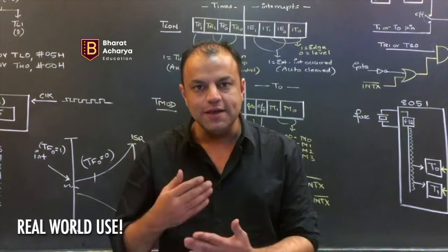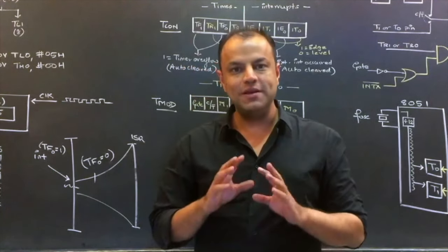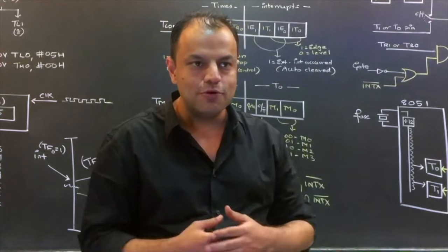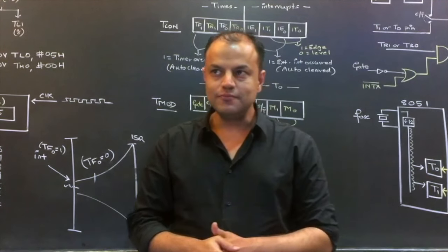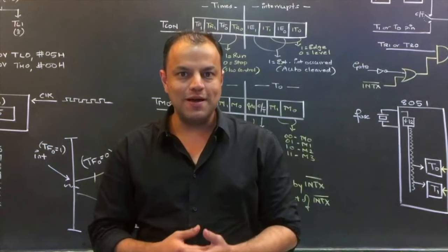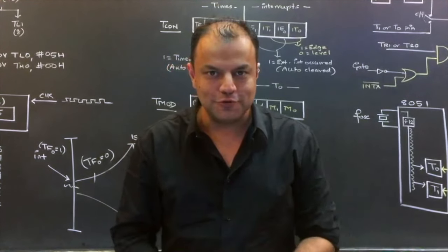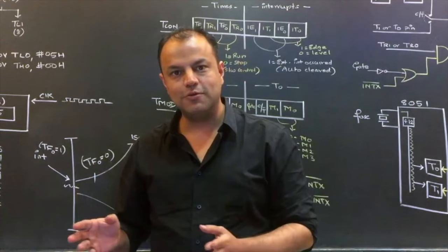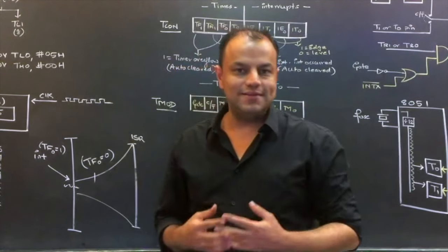So here you need a separate component to produce the delay. That's where timers come into the picture. Please tell me, did you understand why you're learning this chip? Take your mobile phone: you've kept an alarm for tomorrow morning. That means that alarm will trigger tomorrow morning, let's say 7 o'clock or whatever time you get up. So you've kept a delay from now till that time. If you use a software delay, what happens? Your processor is involved in making that delay. From now to tomorrow morning 7 o'clock, you cannot use your phone. Instead, if there is a hardware delay, the processor tells the timer, you count, I am free to do other operations. When your counting is over, inform me. Did you understand this? So that's the idea. So these delays are hardware delays.